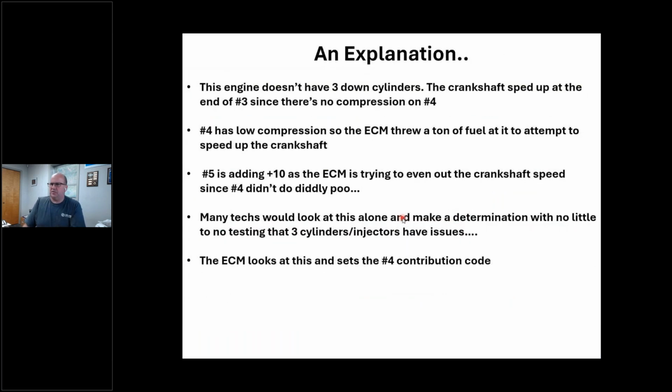We don't have 3 down cylinders here, or before we make that determination, we've got to check the mechanical integrity of this engine. We're going to do our relative compression test. I couldn't do it with the IDS. I'm not sure why, it just kept failing. Now, this thing's chipped up. So who knows? That's probably why it's got problems, because it's got performance modification.